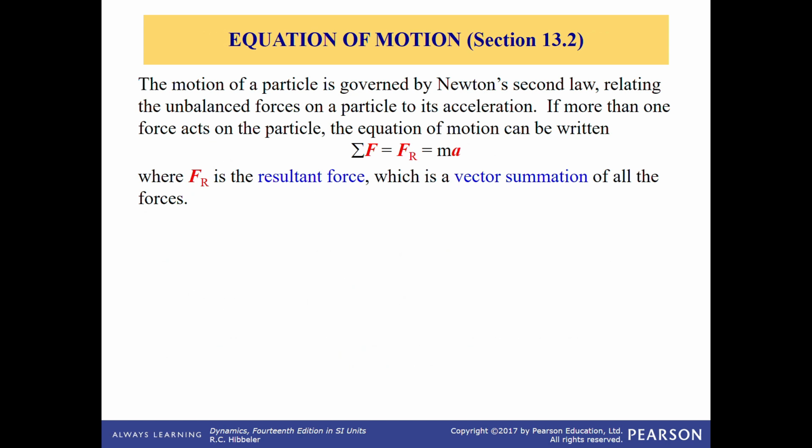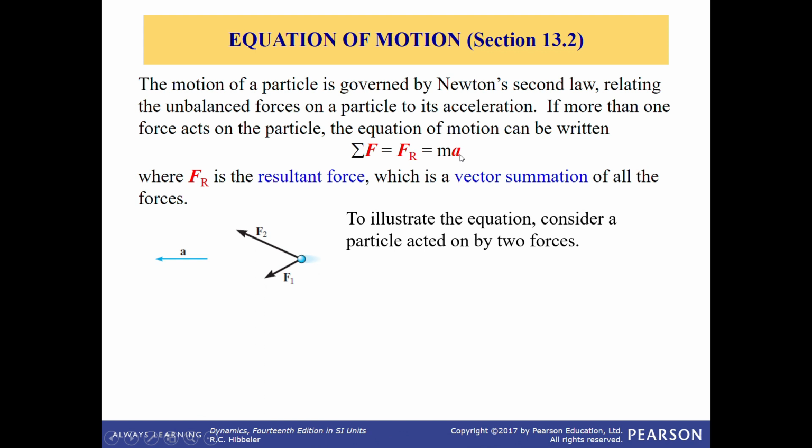Okay, equation of motion. This is section 13.2. The motion of a particle is governed by Newton's second law, relating the unbalanced forces on a particle to its acceleration. If more than one force acts on the particle, the equation of motion can be written as summation of force. So summation of force here is actually the resultant force, and we say this as Fr equal to m, mass, times a. A is the acceleration.